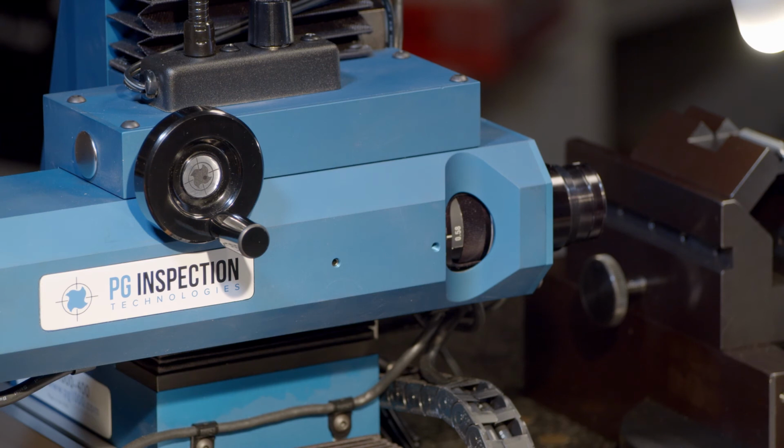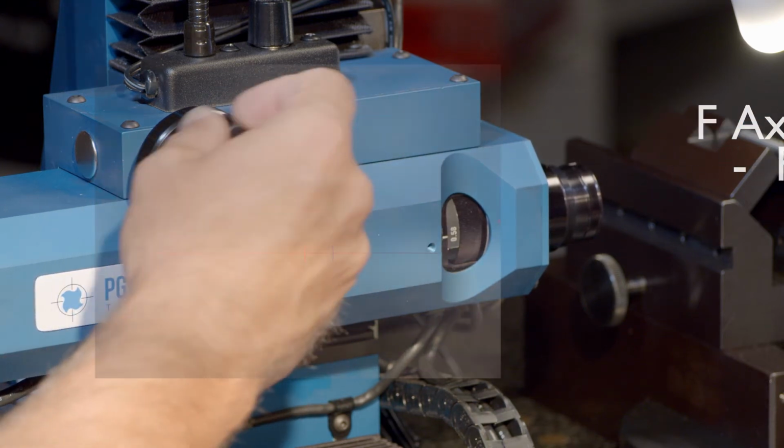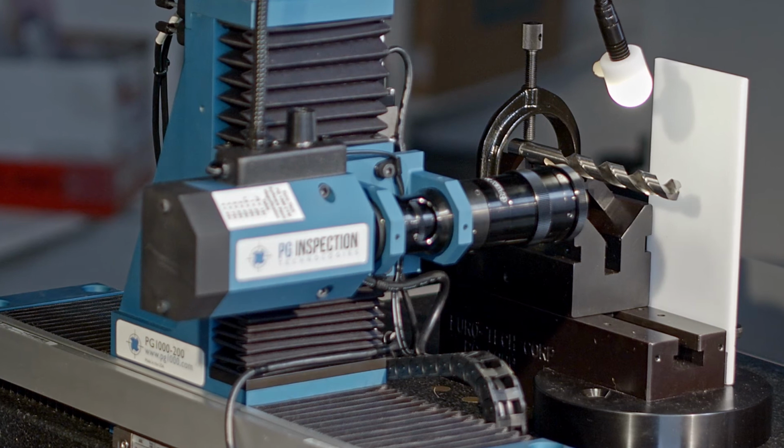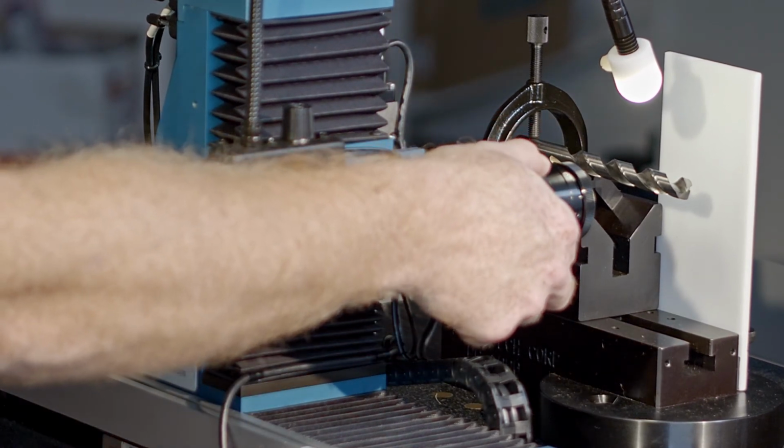PG1000 400 models have an F-axis encoder on the focus assembly of the microscope, which collects and displays the focus location and supplies that data to the software. This feature includes an on-screen focus bar, which allows the user to be more consistent when setting up repeat tool inspections. PG1000 200 doesn't include an encoder for the focus, so focus location must be manually interpreted by the user.